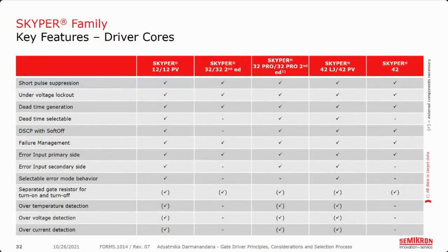Every one of them is equipped with short pulse suppression, undervoltage lockout, and internally generated dead time, and of course the general failure management. On top of that, you may choose which features you need for your application. Please take note that the points inside the brackets mean that you need external components to make these features work.